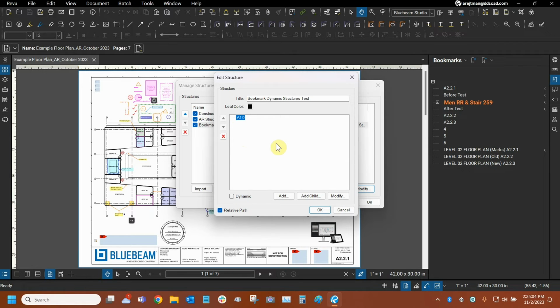So I can essentially make the 1.0 versions of whatever disciplines I need. And so the architectural one could be ready. Then we could have B, for example, if we do have a discipline with that letter, S for structural, et cetera, et cetera. And then E for electrical. So we could have all of those ready, but we don't need to have every single number, just the 1.0 version if we're expecting to have several sheets per discipline. We're just going to do it for architectural for now.